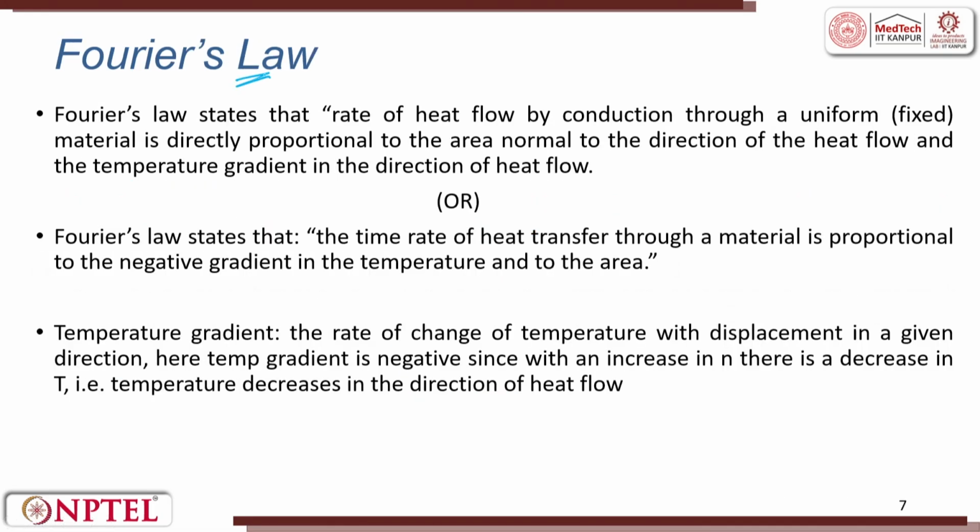Fourier's law is an important law when we talk about heat transfer. Fourier's law states that the rate of heat flow by conduction through a uniform material is directly proportional to the area normal to the direction of heat flow and the temperature gradient in the direction of the heat flow.